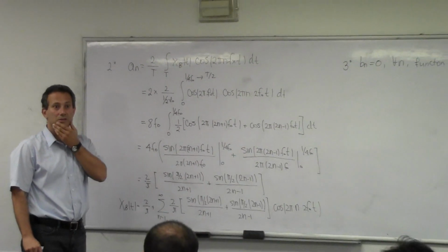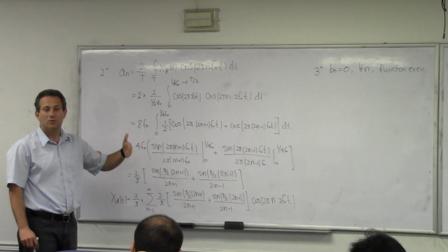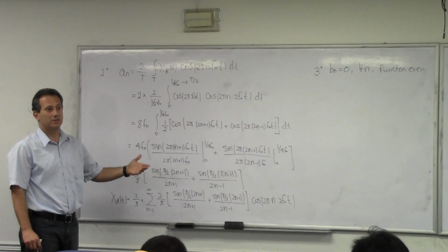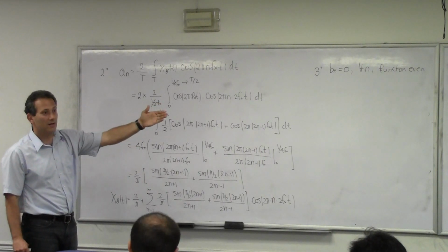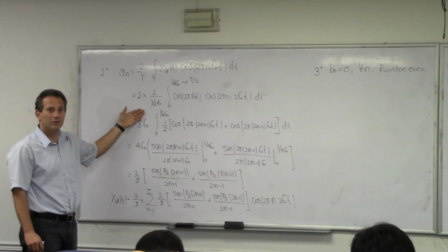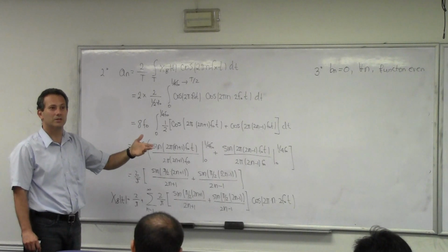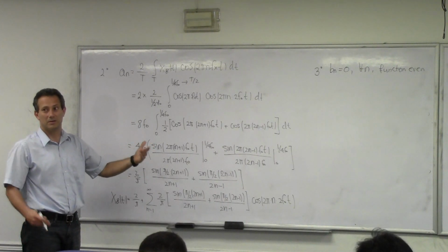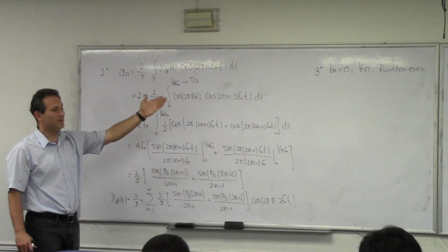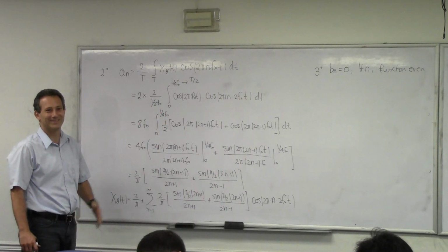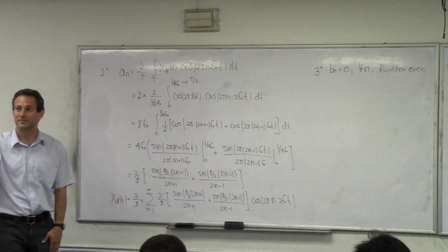Any comments, questions? So it's not difficult, right? You just have to use it systematically, don't be impatient, and as you go along, build these checks. Look for DC value, look for symmetry, those are your best friends, right? If you can discard computing something on account of symmetry, no chance of making an error, right? All my bn are correct, right? Because the function doesn't have it, right? So it's all zero. Go ahead.